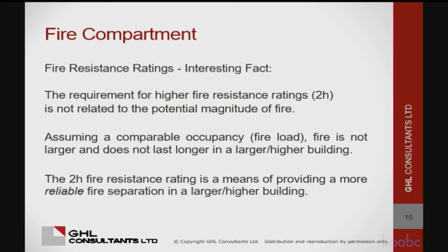So this is an interesting thing that we talked about in the office the other day, and that is, why are some fire separations 1 hour or 2 hours? The requirement for the higher fire resistance rating is not because the fire is bigger or lasts longer in a larger or higher building. It's what Andrew called a ham-fisted method of getting a more reliable fire separation. So a 2-hour fire separation is more reliable than a 1-hour fire separation, but you're probably dealing with the same fire, unless you're in an F1 or some crazy occupancy with a really high fire load.